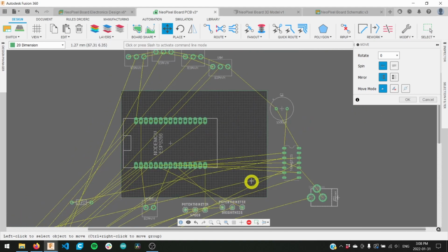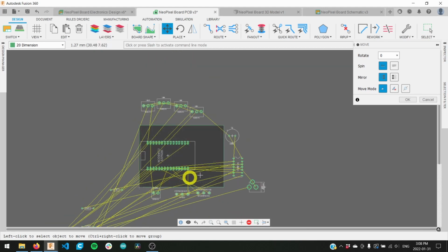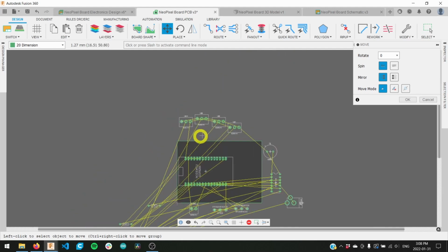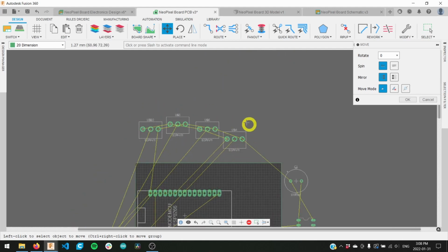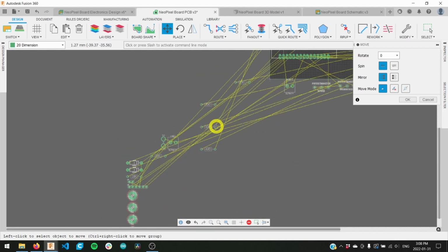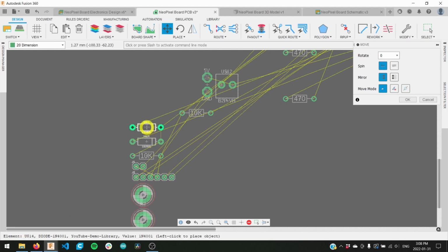And that's going to minimize the amount of crossover action between the Airwires. We want to try and make it as clean as possible. You can see down here it's quite chaotic, but you can already see that up here, when the neighbors are clustered together, it immediately starts getting a bit cleaner and we can make easier connections. So go ahead and fast forward through this a bit.